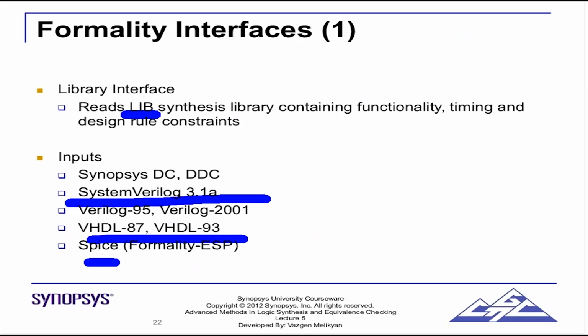because formality again has to match for any tool. Even if you are doing simulation at a gate level netlist, you will need to read the standard cell library Verilog model. Here you can read the Verilog model. Also, you can read the .lib. You can read any one of them, because both of them have functionality and formality understands both.